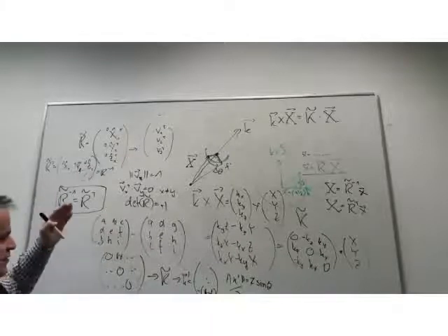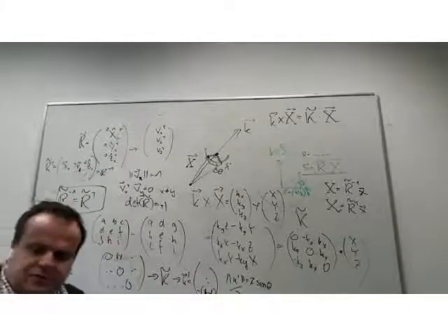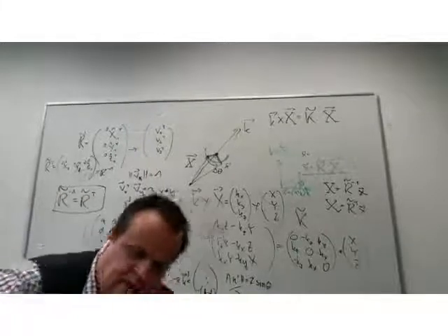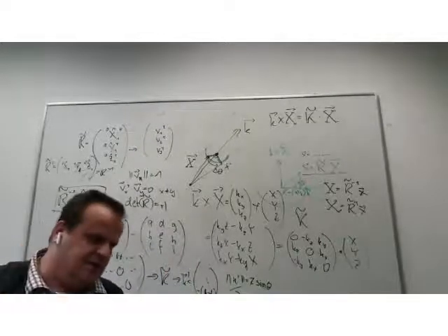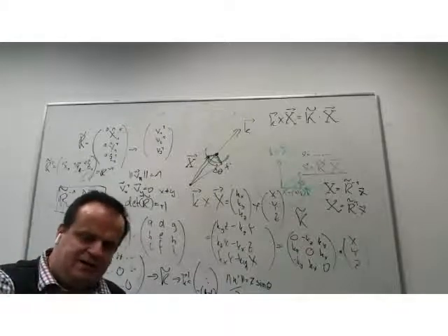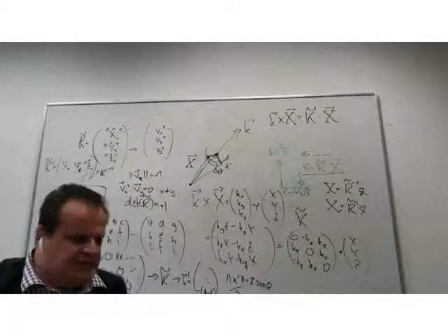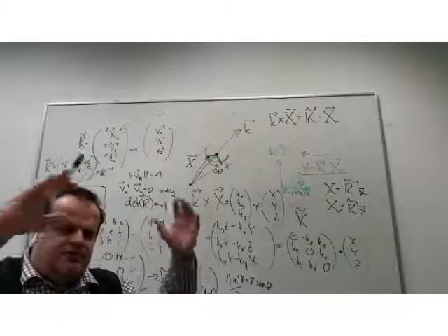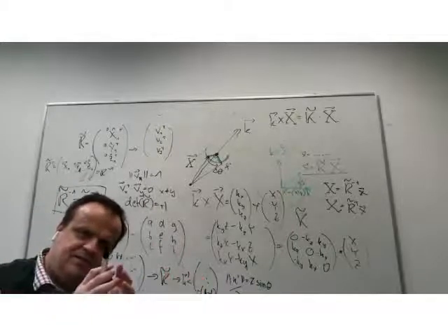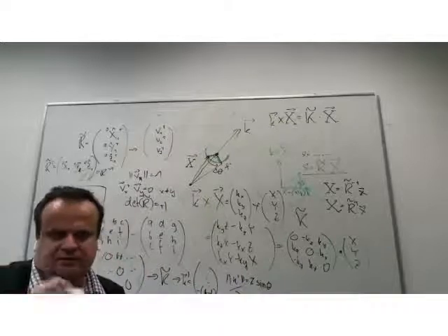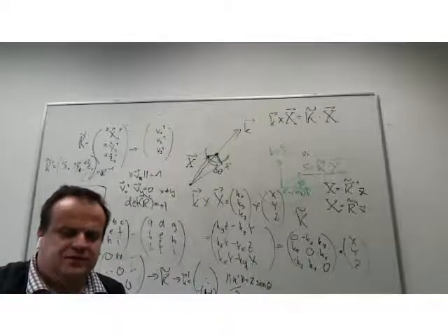If I have 3 rotations, you've seen it already with the elementary matrices, I just multiply from left the sequence of rotations, and the sequence is always from right to left. And this gives me the final rotation. I can also multiply the entire product of these 3 matrices and use them as an intermediate result to deal with the rotation.